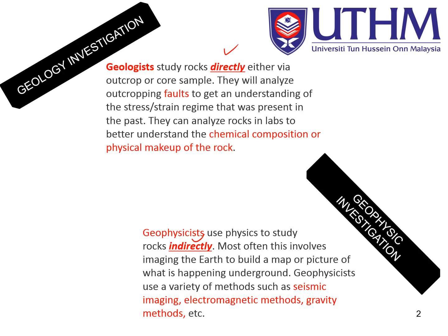For example, is it a fault, bedding or foliation, and then aperture, and they will measure the dip direction and dip angle. If you still remember in lab 4, the raw data from table 1, that data represents the raw data for discontinuity for a site.